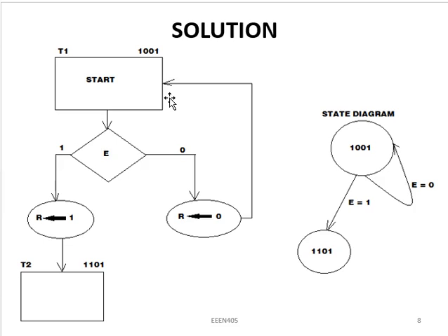And additionally, after drawing the ASM chart, sometimes we are asked to draw a state diagram. And if we can remember how we did this under sequential logic analysis, we'll remember that what we are concerned with here are the states. And if you look at this, I have two states. I have state T1 and I have state T2, and I'll write two circles for T1 and T2. I don't write the T1 and T2, but I'll write their binary codes. This is 100 and this is 110.